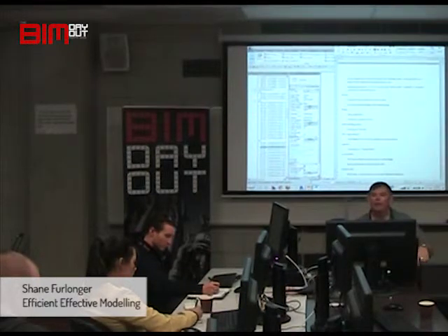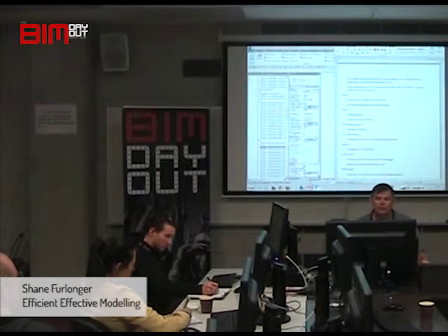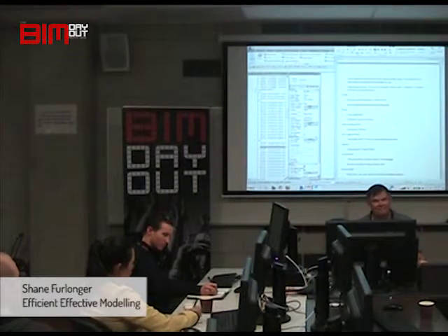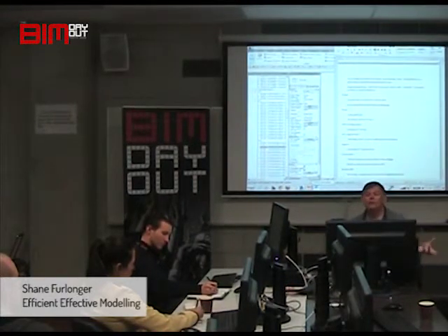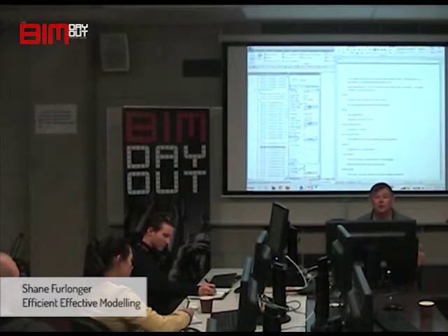Are you restricted by what you can add into assemblies? Yes, you are. Curtain walls don't like assemblies. That's a bugger. You can put in the mullions and the panels though. You can't put a system, but you can put a curtain panel. Which doesn't help much really. But for internals, for walls and doors, assemblies are really useful. Mainly because if you want to make a global change, you can do it, which you can't do with a group.